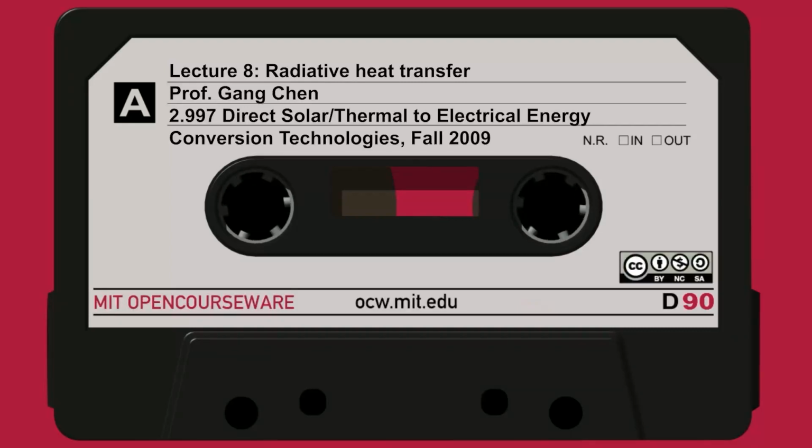So for thermal radiation, Planck's law is usually considered the maximum, and we define the intensity as the power leaving the surface in a certain direction. So that's the intensity. It's different from power. This is the power in this direction that we characterize by solid angle: the power in this direction per unit solid angle, per unit area normal to the direction of propagation, per unit wavelength. So this is what we mean by intensity. It's propagating in this direction.